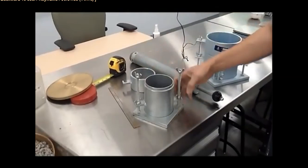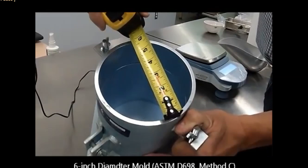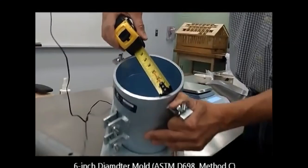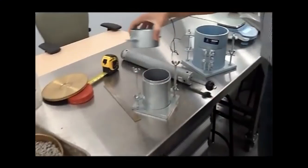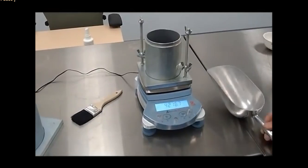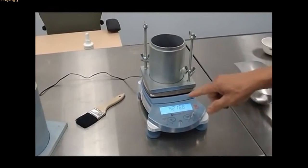Before I take the empty weight of the mold, I should measure the volume of the mold. How do I measure the volume of the mold? I will measure the diameter of the mold, and I will measure the height of the mold. So area into height will give me volume. So the volume of the mold is taken, the empty weight of the mold is taken, then we'll start the experiment.